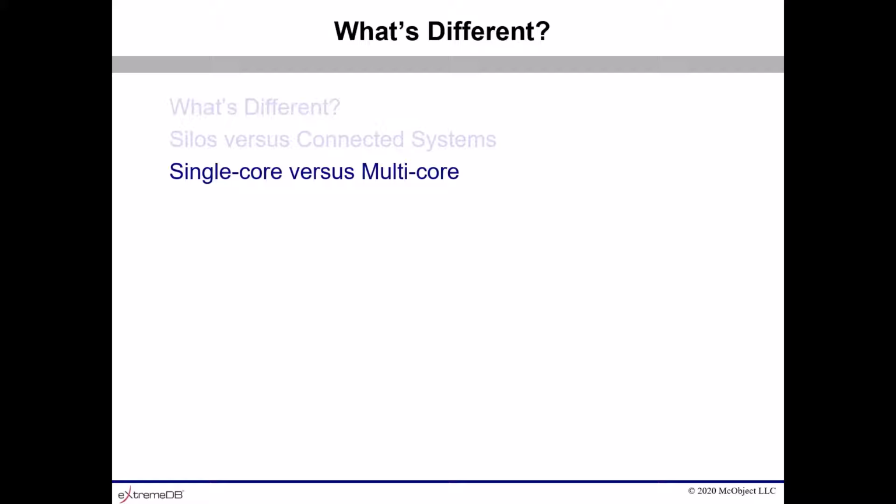So when you're researching your choices for a database management system for your edge device, look into its ability to leverage a multi-core architecture, or at least not hinder your ability to leverage a multi-core architecture. To put a finer point on it, some implementations of the C runtime library for embedded systems toolchains are still rather rudimentary, and a database management system's reliance on the C runtime library can defeat concurrency in a multi-threaded application. For example, relying on malloc and free to manage heap memory.